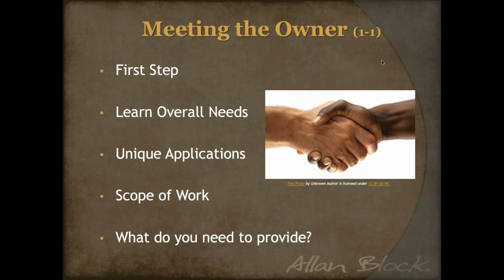Another thing is that this is the best time where we can learn about the overall need for the site. Is it going to be a commercial or a residential site? Is it going to be a government project? Are there going to be surcharges above the wall? Any drop structures or property lines that might interact with the wall or the reinforced zone? Are there any building foundations that need to be addressed? So all of these types of needs for the wall are things that the owner might know offhand, or they might know that the site is going to be used for something where one of these might come up.